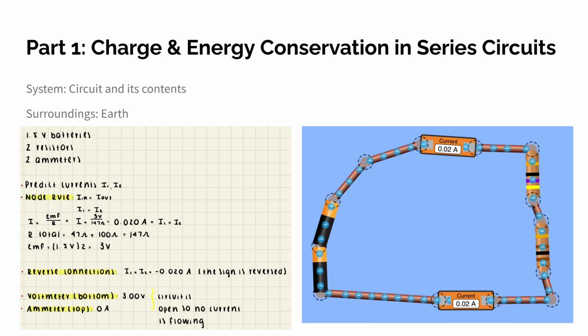If the connection were to be reversed, the only thing that would change would be the sign of the current. The value of 0.02 amps would remain the same. Furthermore, when replacing one of the ammeters with a voltmeter, the circuit was open. This means that there is no current flowing through the circuit, so it marked that the ammeter had 0 amps.